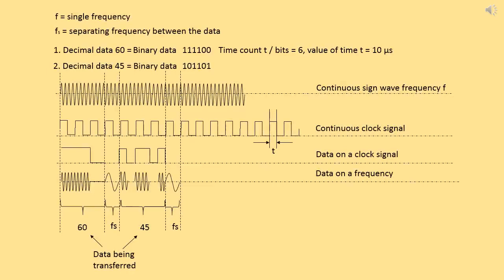This can be accomplished by first using a single frequency generation, then the slicing of the same single frequency with the help of a clock signal that carries the data upon it, and then the storage of the frequency value, in binary form only once, in the 8-bit clock data into the memory. The frequency value corresponds to or remains analogous to the resolution level, whereas the 8-bit clock data is the data information.